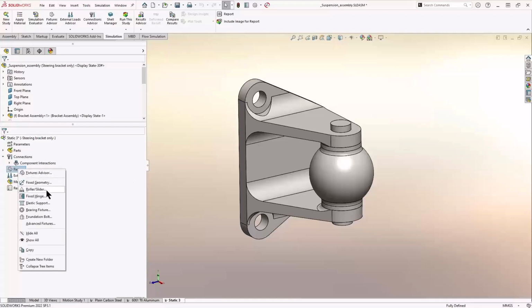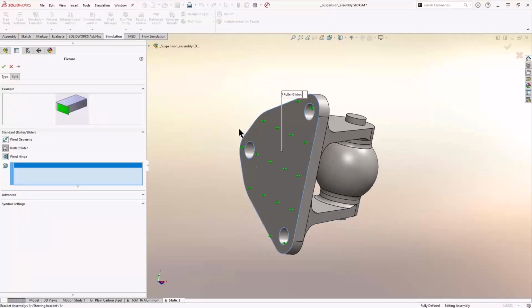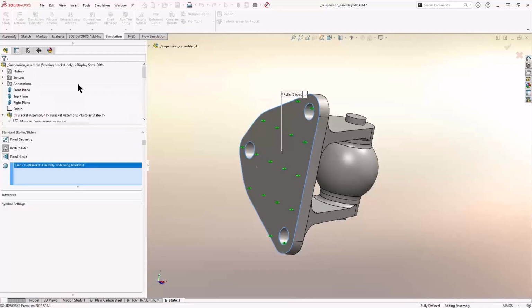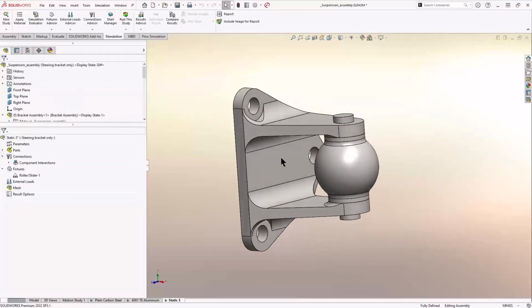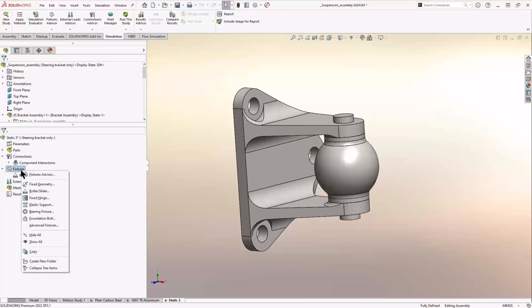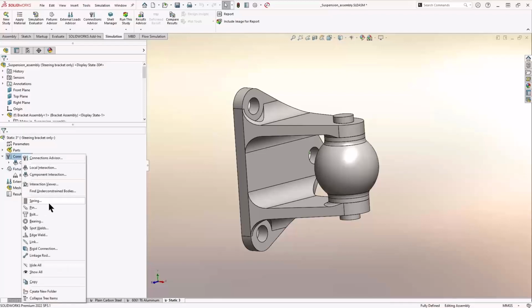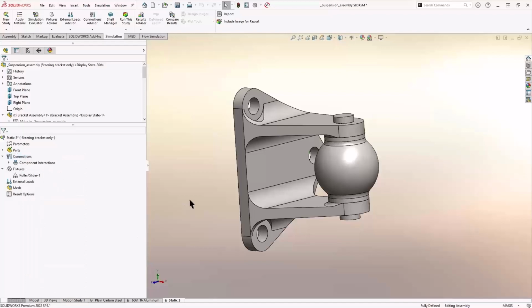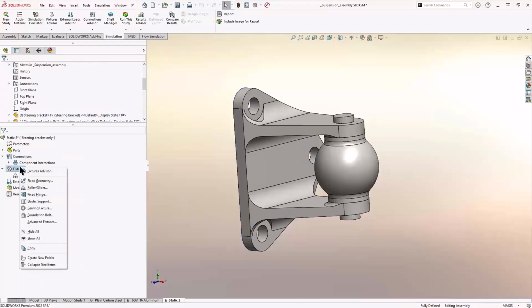By fixturing, I mean all that stuff I suppressed. So one easy fixture here would be to apply a roller slider on this back face. Basically, this face is bolted on a material that I've suppressed, so it can't move in that direction. There would be material here holding it and saying, you can't move in the X direction. The other thing is that it's actually bolted to those materials. And yeah, I could go do a bolt connector. There's actually all sorts of connectors, bolts, springs, edge welds, links, but I'm going to keep things simple, man.